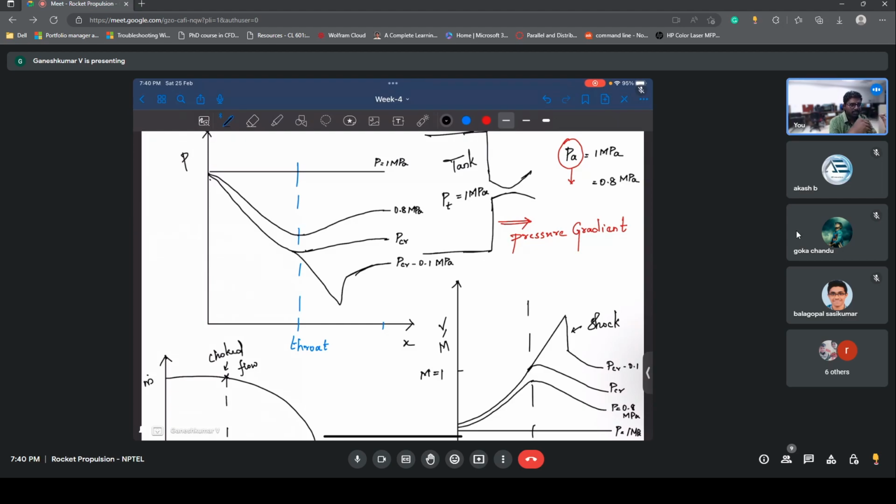So what I have to do is decelerate suddenly, right? This is Mach number greater than 1, very high velocity, and I need to suddenly decelerate. So what it has to do is form a shock wave. So that's where the shock wave comes in. What happens in a shock wave is a sudden change in properties, or a discontinuity in the pressure.